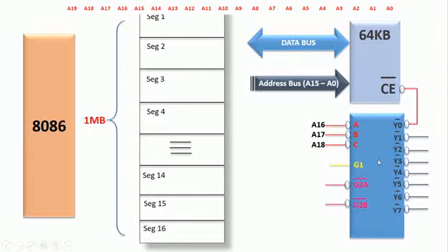Okay, now how many control lines are we having? How many enabling signals are there for this address decoder? Three signals, but we are left with only one address line. It is up to you. You may use A19 to enable G1, or you may use A19 to enable G2A bar, G2B bar. That is the active low signals.